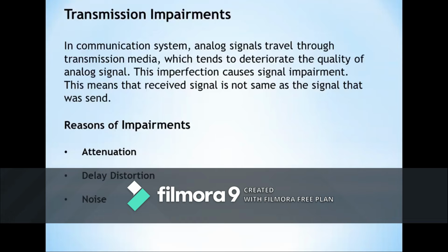The signal without baseband filtering also has crosstalk if the pulse tail or post cursor overlaps into the next time slot of the frame. Pulse overlap can be controlled by using guard time between the pulses. The guard time is analogous to the guard band between the channels in an FDM system.